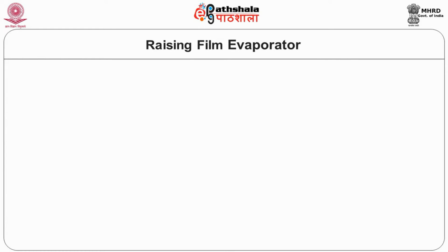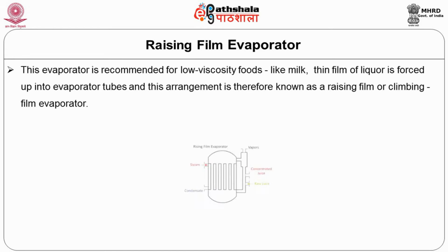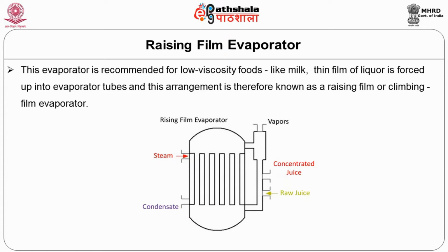Rising film evaporator. This evaporator is recommended for low viscosity foods like milk. A thin film of liquid is forced up into the evaporator tubes, and this arrangement is known as rising film or climbing film evaporator.